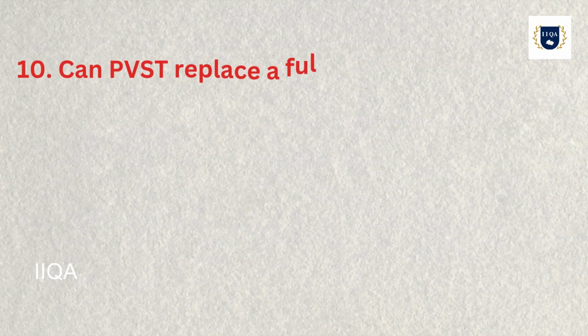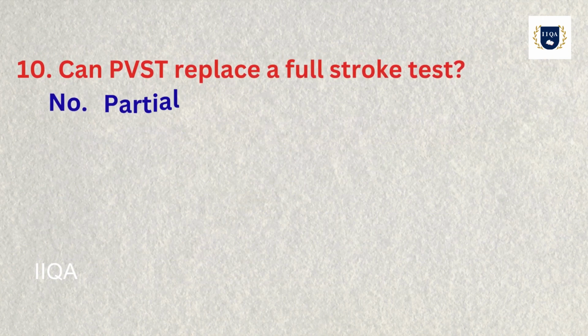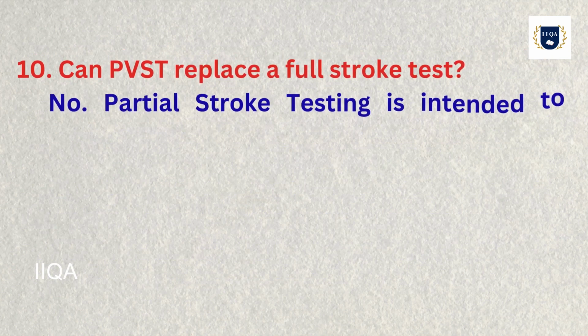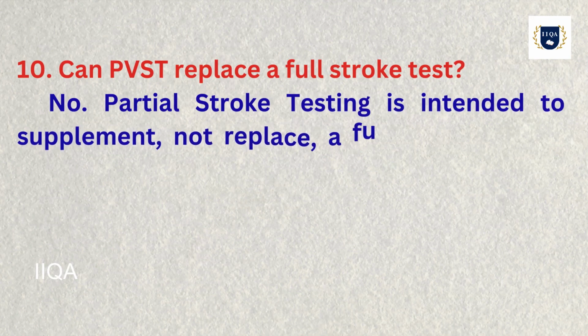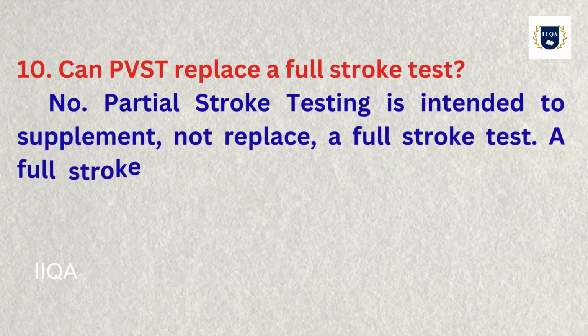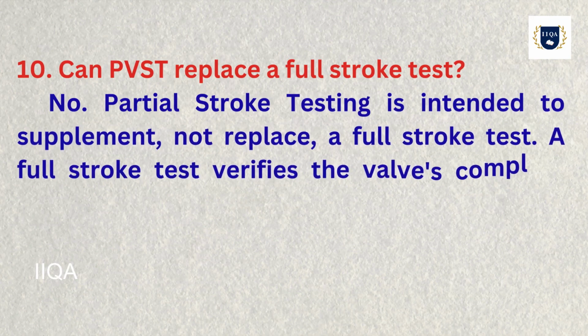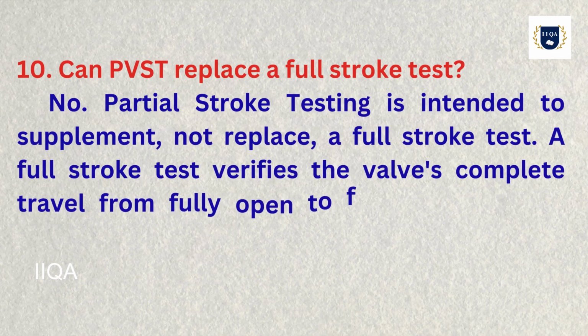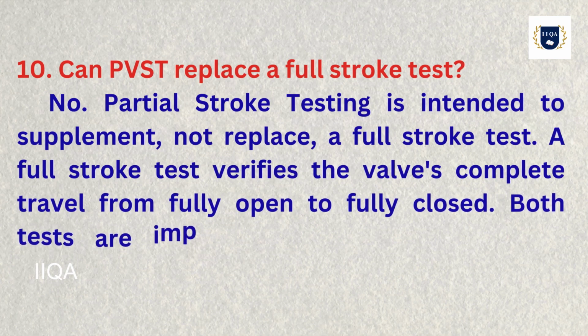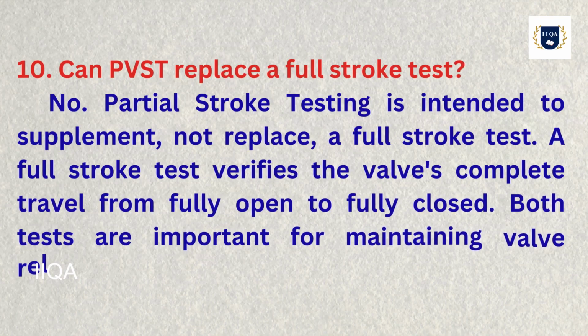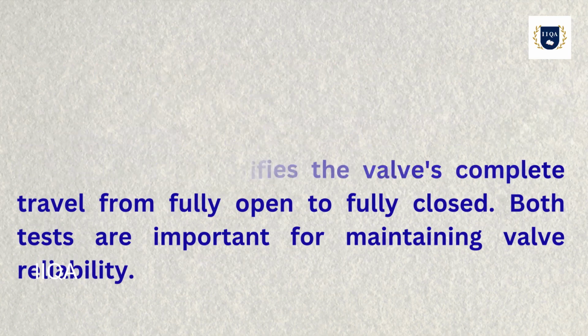10. Can PVST replace a full stroke test? No. Partial stroke testing is intended to supplement, not replace, a full stroke test. A full stroke test verifies the valve's complete travel from fully open to fully closed. Both tests are important for maintaining valve reliability.